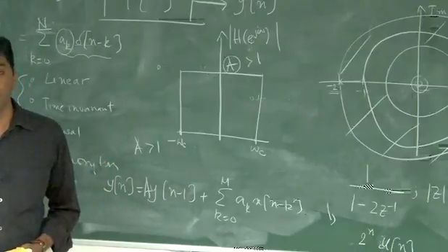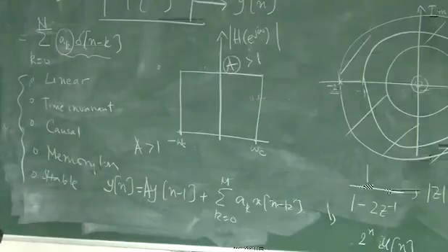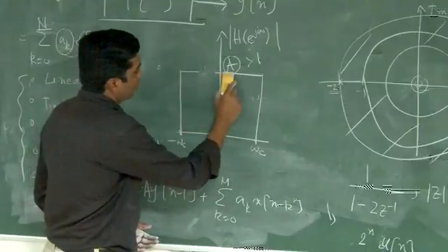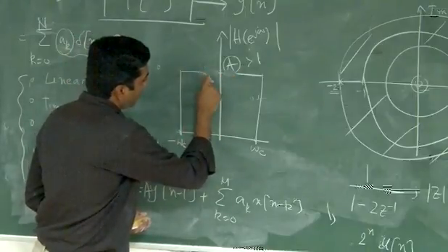So what are we doing in that case? Based on the knowledge that you have acquired so far in this class, when you say that you're turning down the bass, what are you doing? So bass, do you think it's high frequency or low frequency? Low frequency, right? So when I'm turning down my bass, what am I doing? I am actually changing the system response so that signals in the low frequency range are going to be attenuated, right? So how will that modify this here? So I'm perhaps trying to do something like that,